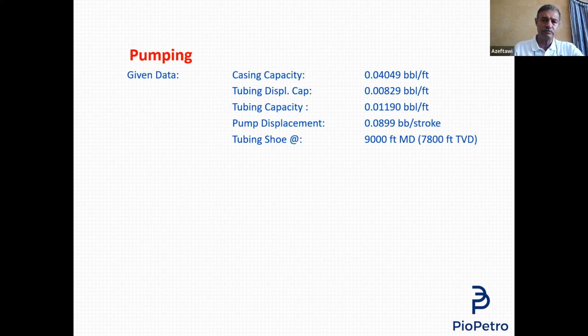So the tubing volume is how many barrels I can fill the tubing with. But the displacement volume is the amount of fluid displaced by the metal thickness. So back to my well, it is full of 500 barrels of water. I run the production tubing all the way in, 50 barrels is out. What is this 50 barrels? We agreed that this is the tubing displacement volume. My second question: what is the total volume of this well now?